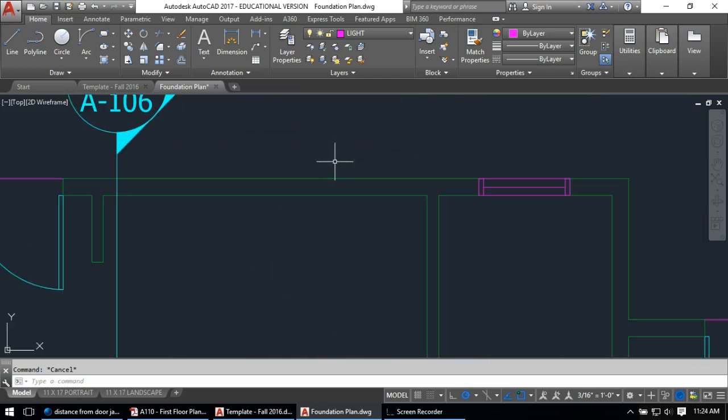I've got one more window to do, which is a 48-inch window that is 8'2" over. So I'll draw the center point there, offset 8'2", and then offset 2 feet because it's a 4-foot window. Whoops, what did I type in? Try this again. And end my command, offset 2 foot there to there.